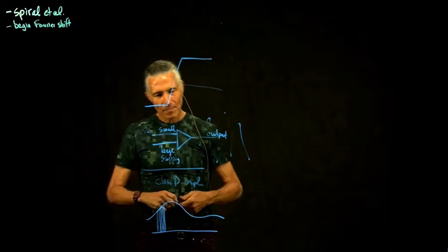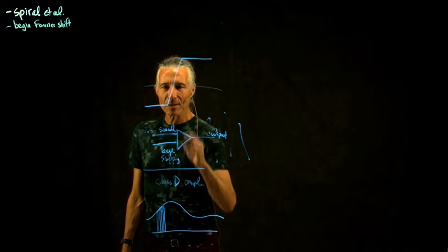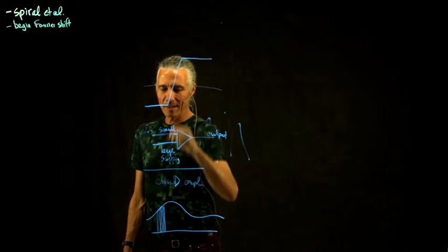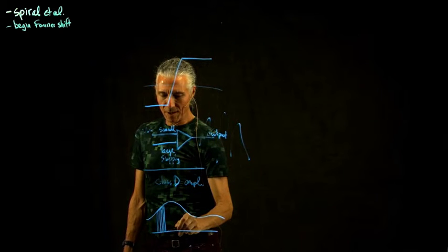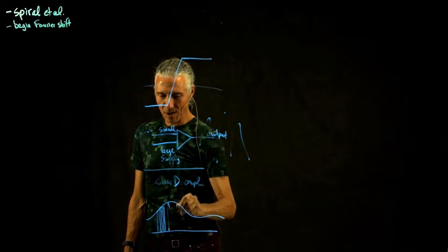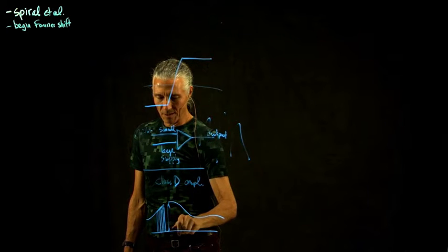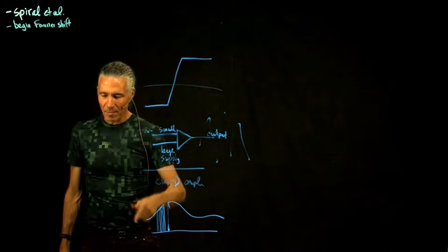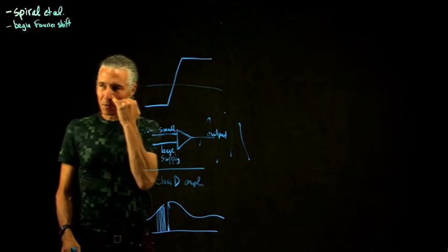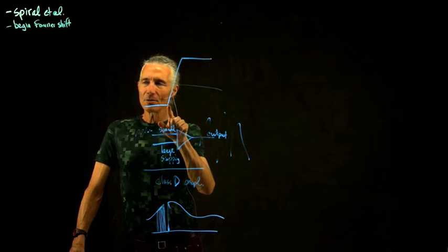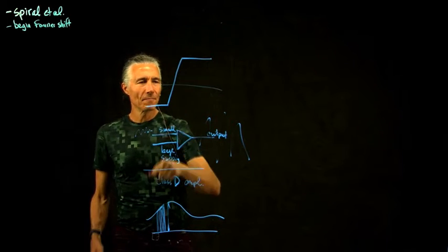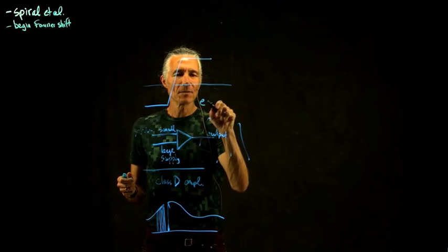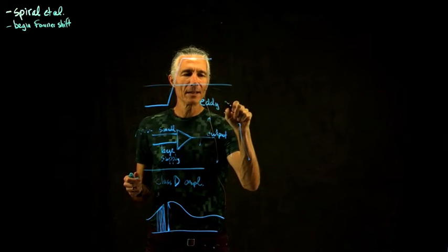This is the way the amplifiers work now, and so they can do something like this. They can do a better job of something like this, because you should be able to just turn the amplifier off and then suddenly turn it all the way on. So in theory, you could make something that looks just like that. But it turns out, because of that feedback loop aspect, it's really hard to do something like this. In fact, the reason, which I was sort of beating around the bush about, one of the problems is called eddy currents.